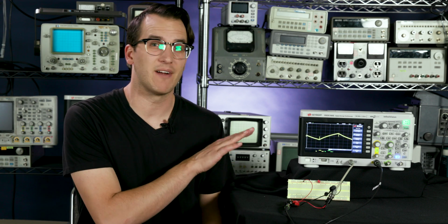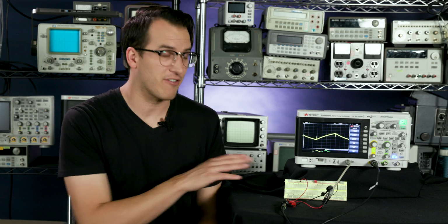Now, if you've prototyped with breadboards before, you know you're already set up for some issues here because inductance and capacitance is in everything, and breadboards and these jumper leads are notorious for having unwanted capacitive and inductive effects. This glitch is a side effect of how capacitance and inductance, and likewise capacitors and inductors, respond to an AC step response. So let's pull out the whiteboard and look at the step response of inductors and capacitors, and look at the effective circuit that I have here, not just a single capacitor.